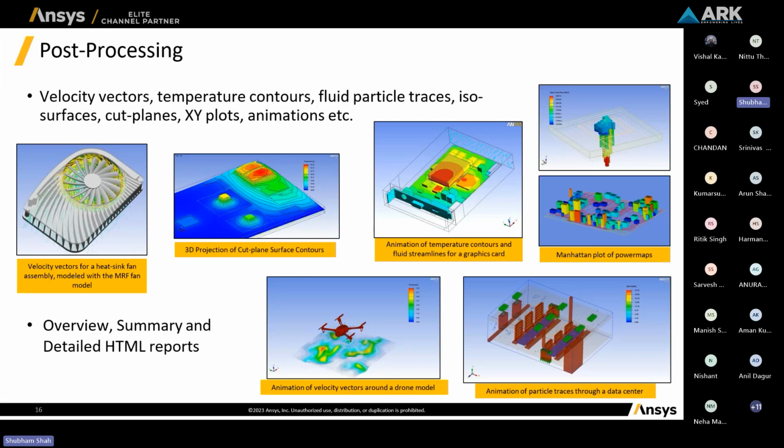So when we proceed with the simulation in this case, how your geometry is created, in which coordinates, that will also play an important role. If your geometries are created in the negative coordinates, your 950 will act as a negative, anti-clockwise. So you have given the positive value, but your fan will rotate in the anti-clockwise direction. Our aim was to see whether the fan rotates. It should rotate in the clockwise direction.